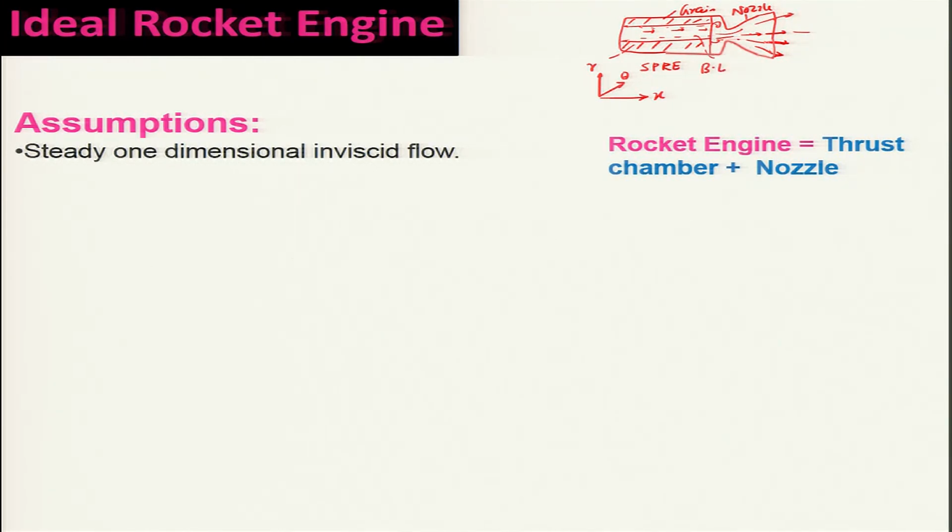and however, as the boundary layer will be small, particularly in the nozzle, the flow will be at very high velocity, it is accelerating, the boundary layer will be small. So, therefore, we can consider the flow to be inviscid in nature, and the details of combustion are being ignored because it is quite complex.